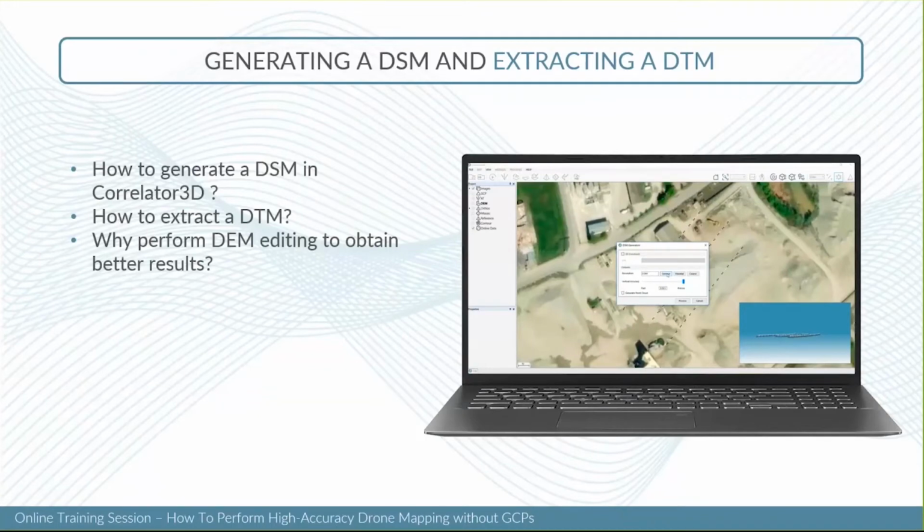However, with data like WingtraOne data, you could probably lower the resolution a bit and go to maybe 3 times the ground sample distance, adding sharpness to your output and really having the best quality data possible. If you go lower than that, such as a pixel value like a 1-to-1 matching, you may add a bit more noise to your project. So we don't really suggest going below 3 times the GSD of your images.